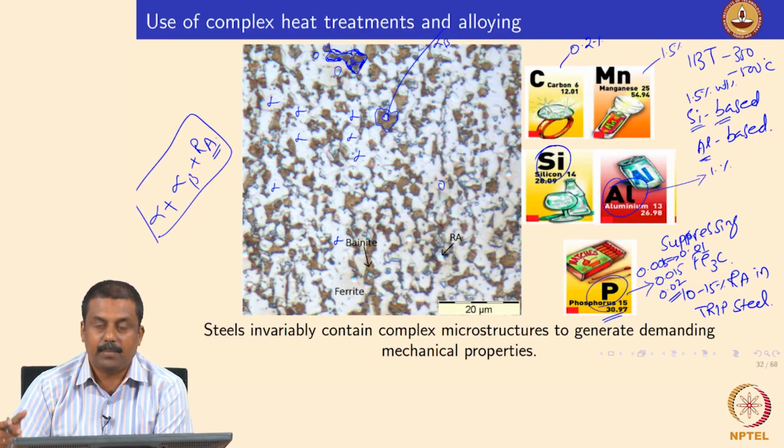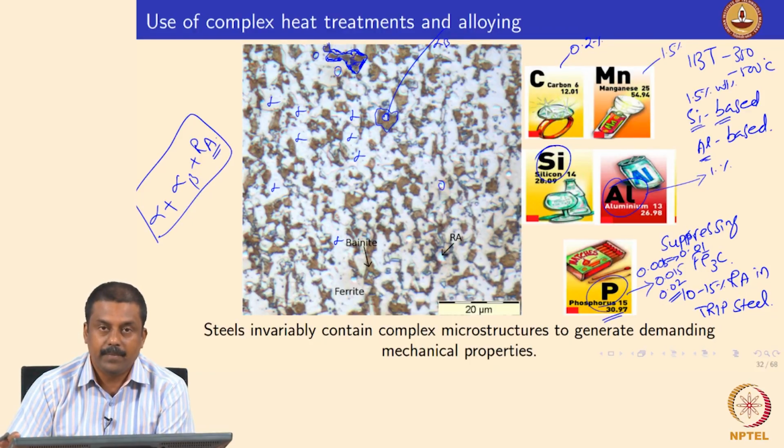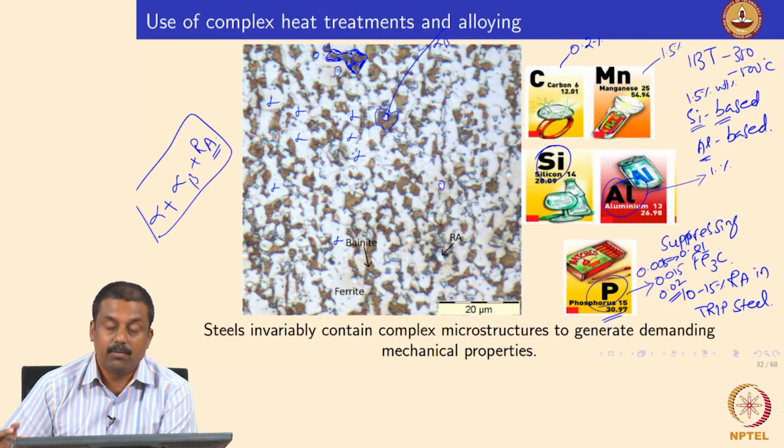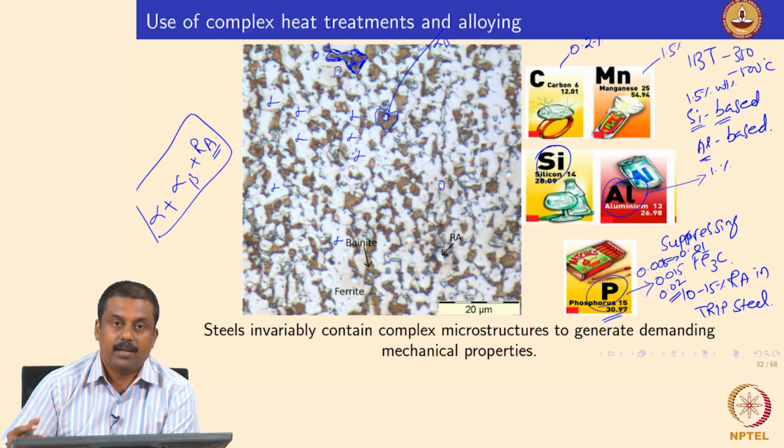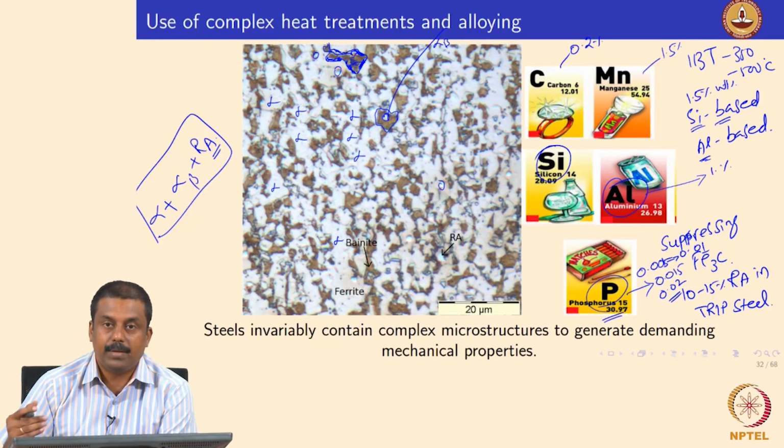During this process, we suppress cementite, thereby enriching the untransformed austenite in carbon, and upon sufficient enrichment, the austenite ceases to transform to bainite. Subsequently, when you cool to room temperature, because of the enrichment in carbon, the Ms temperature decreases significantly, and the Mf temperature goes down below room temperature.